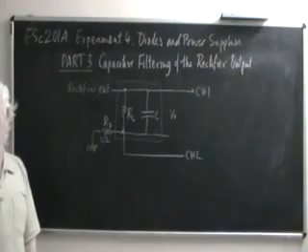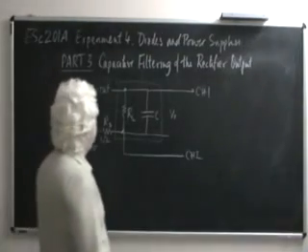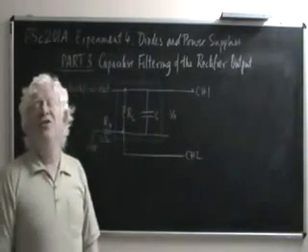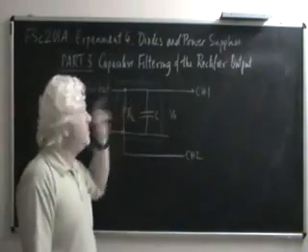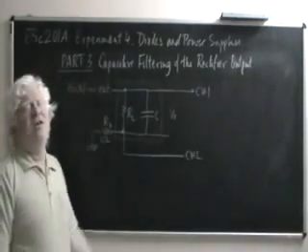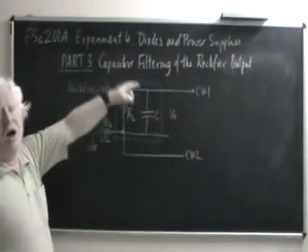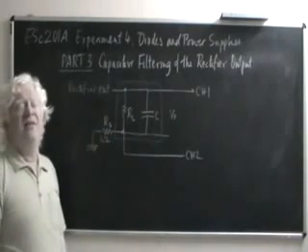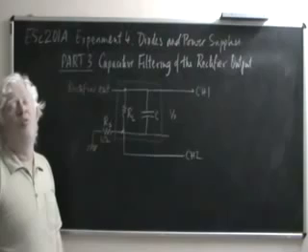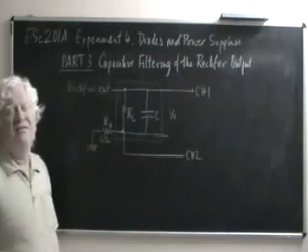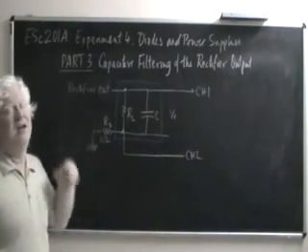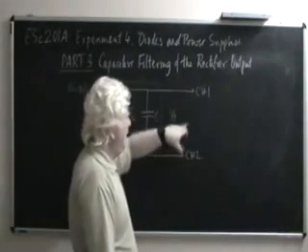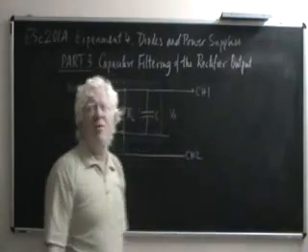What, however, is happening is that the voltage that is measured by channel 1 is not really the voltage across RL. It is the voltage across RL plus RS, and that is not accurately the output voltage. It would therefore have been ideal to put a difference amplifier between these 2 points and send that to channel 1.